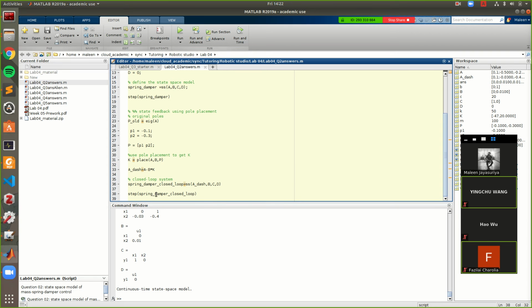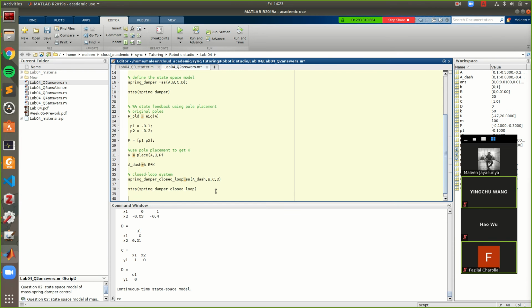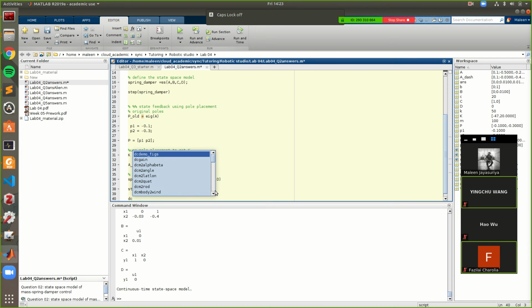How you do that is in this step response function. The problem is the MATLAB step response function will always give 0 to 1. But for it to actually stop at 1, we need to give it 1 multiplied by something else. This steady state value that it stops at is called the DC gain of a system. MATLAB helps us calculate this DC gain using the function dcgain.